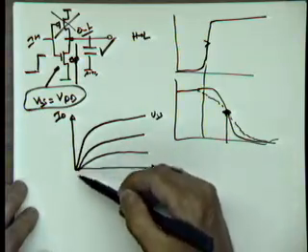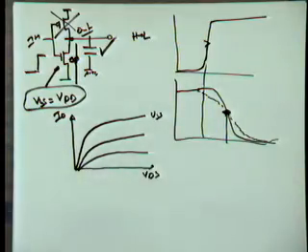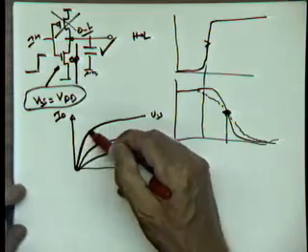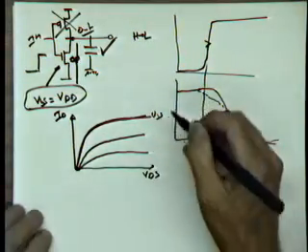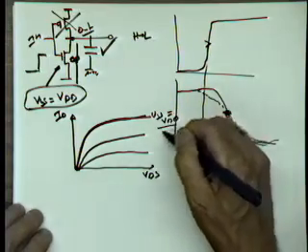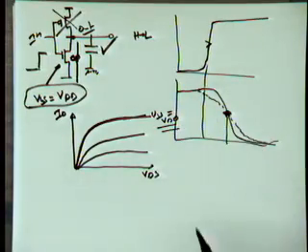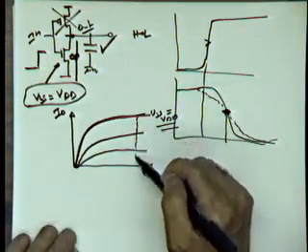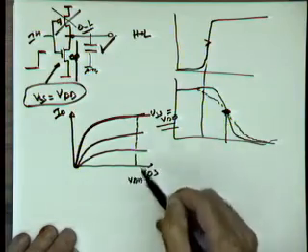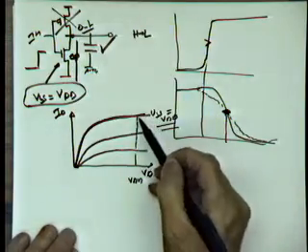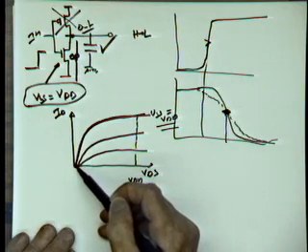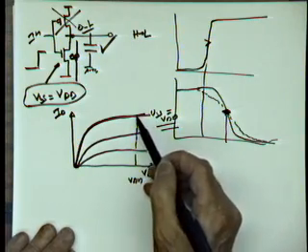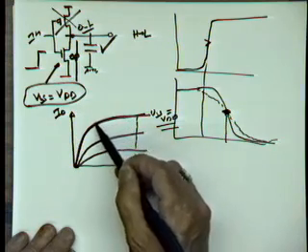It means that the whole transition is going to happen on this curve here, the curve where VGS is equal to VDD. Okay? So we're going to start here, because we start with VDS equal to VDD, that's the first point. And then we start discharging. The voltage is going to go down and down until it gets to 0. But the current is always going to stay on this curve.